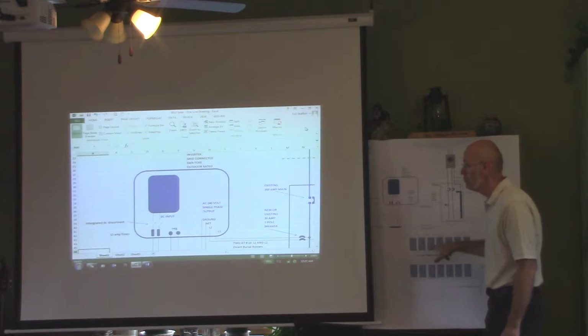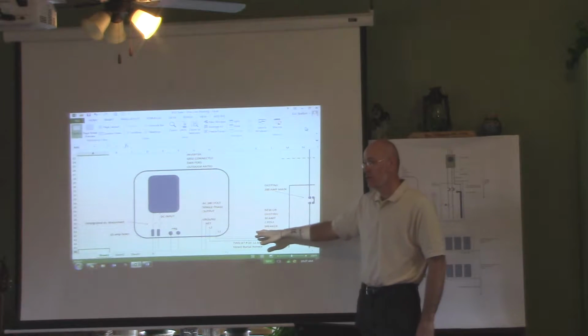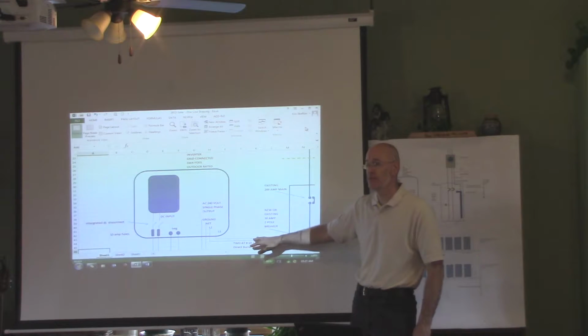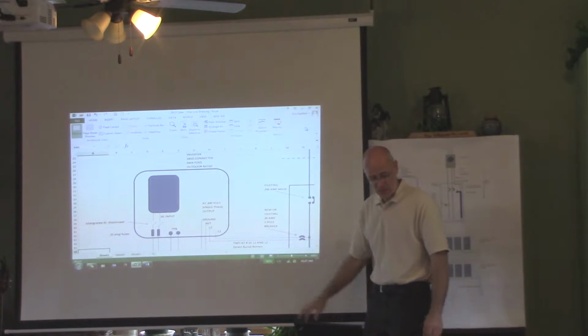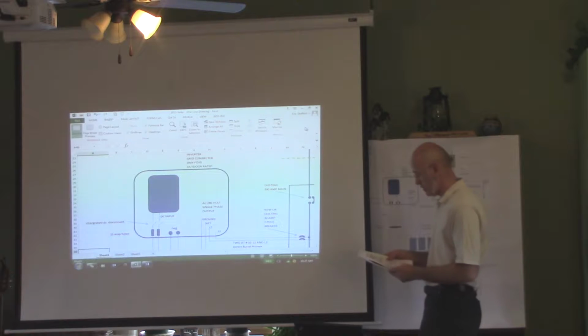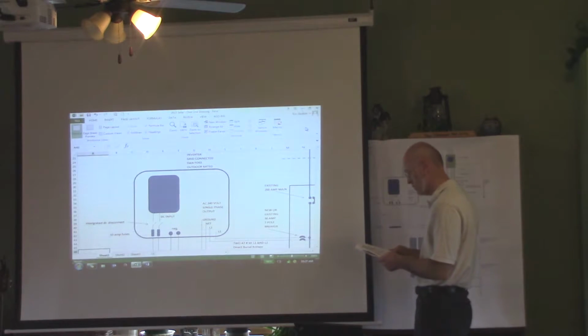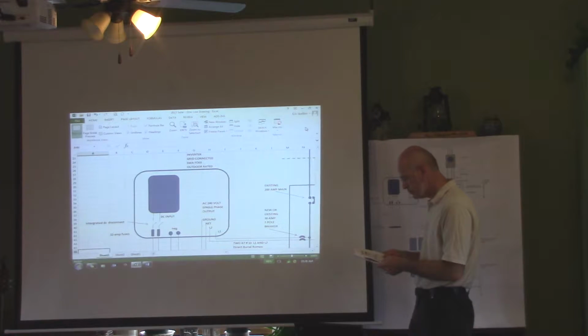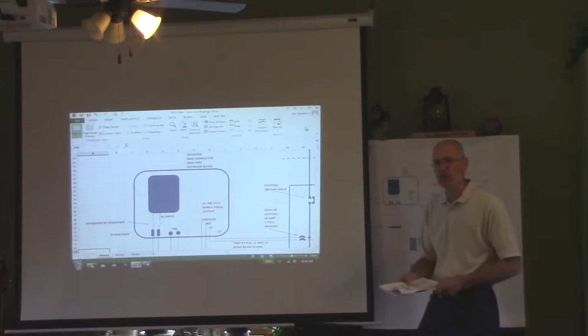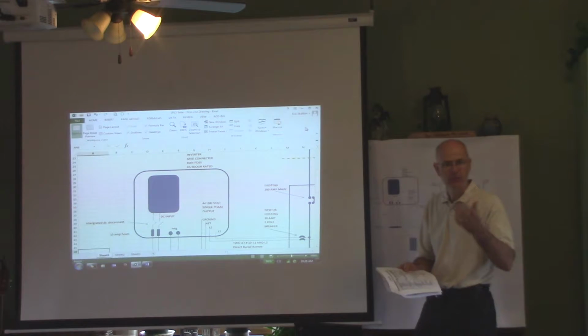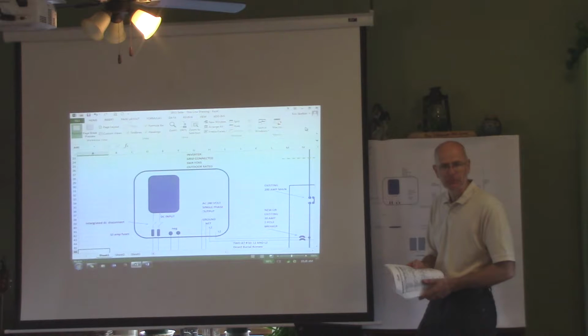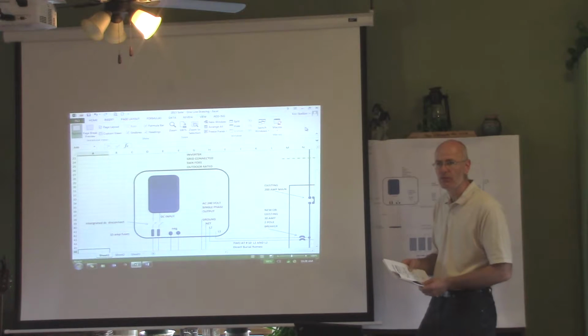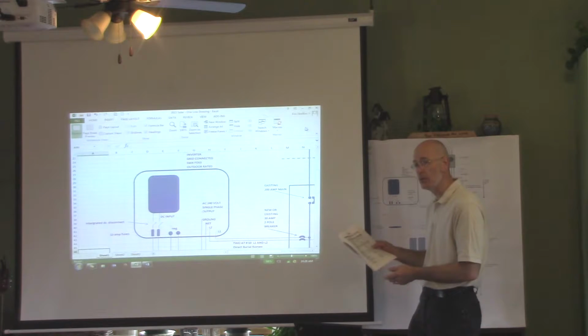So now, my amperage is no longer 14 amps. It's 14 plus 20%. Does that fit with our inverter? Maximum operating current, 21 amps. So what's 1.2 times 14? Oh, 20% more than 14 is another 2 or 3 amps. So we're still below the 21.